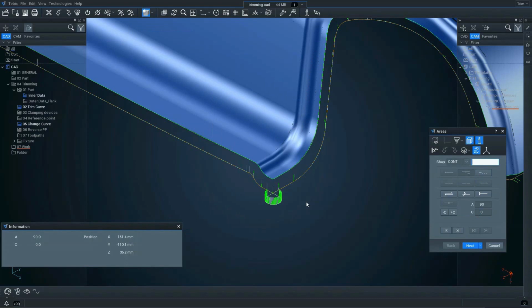And what we have now is the toolpath hasn't been interfered with, so you can still see our perfectly aligned vectors and nice smooth movement. But what's happened now is the tool comes to the end of the cut, comes out of the material, disengages completely, rolls around and then re-engages in a clean smooth movement. This eliminates the chance of this corner snatching, creating a poor surface finish or indeed breaking it off completely.